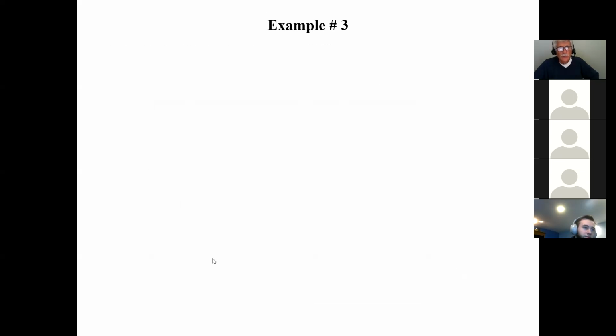So we start with the upper roof. For the upper roof, we say that S is equal to IS, SS, the same thing that we did before. It's almost assuming that the building is all by itself. And as a matter of fact, that's what is actually happening. That building will not be affected by the lower roof.